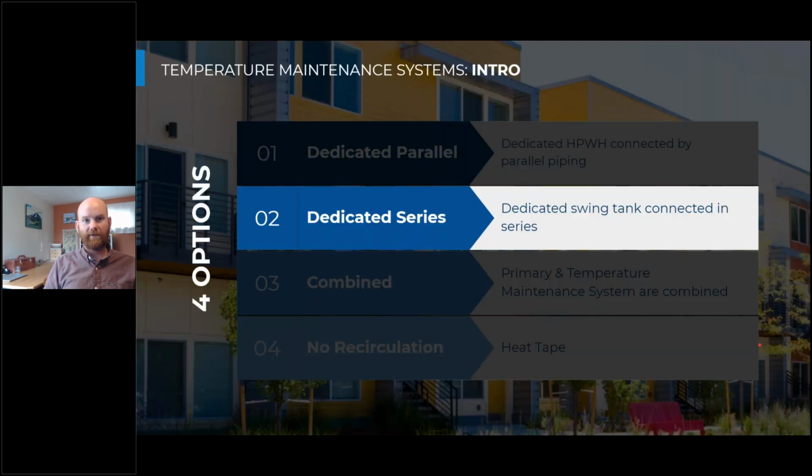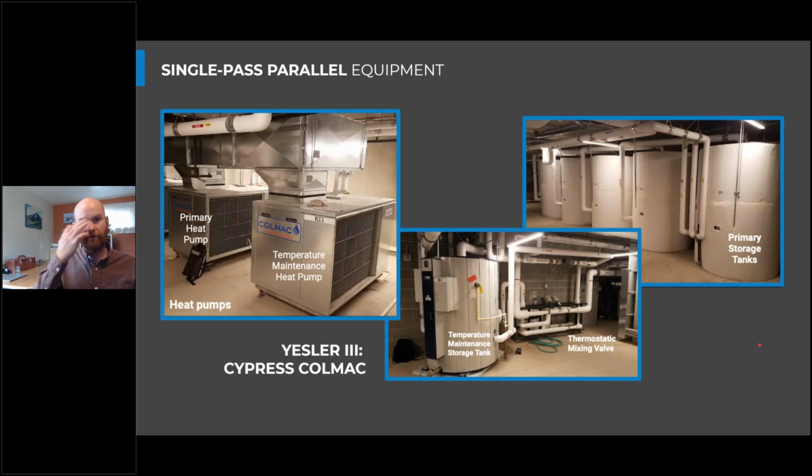This is a really great, proven, reliable and robust design with these larger multifamily buildings. We do have a piece of equipment that may be new or extra, but if we look at this system sizing as a whole, this heat capacity would have been in the primary heat pumps if we would have returned to primary, except we would have resulted in a lower efficiency of those primary heat pumps.